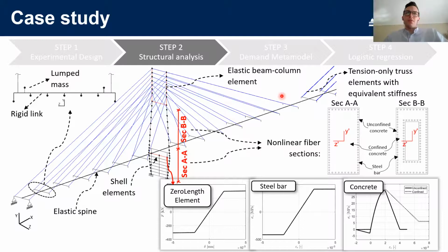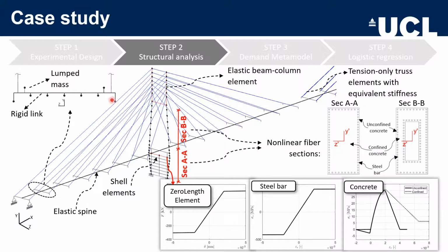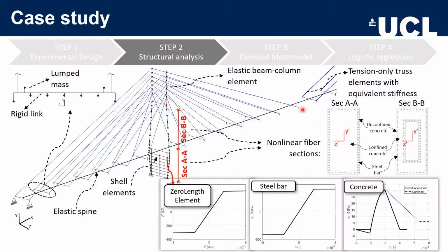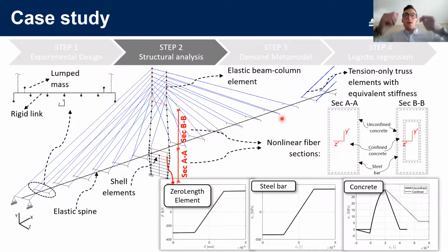I forgot the second one, sorry. The second one was about horizontal displacement of the deck and rotation at the end of cables. But I think you have already answered this, that it's considered by equivalent stiffness. Yes, am I right? Yeah, exactly. So the cables are not rigid, if that was the question. So yes, definitely. Okay, so there are truss elements with a stiffness, so the torsion rotation of the deck is allowed.